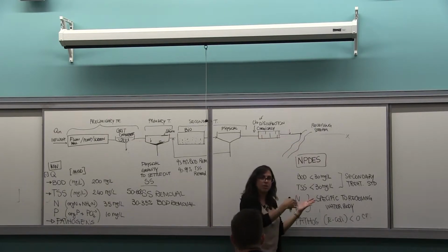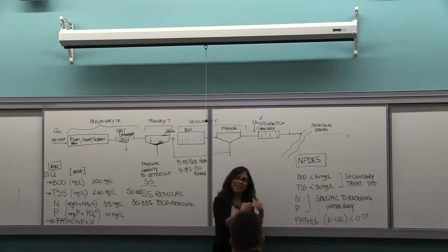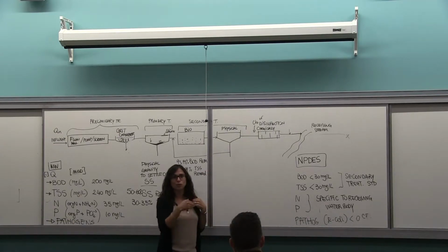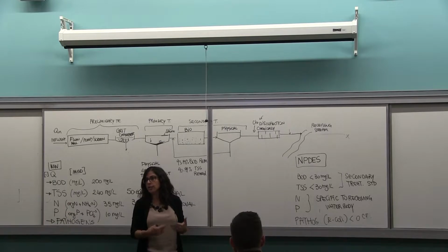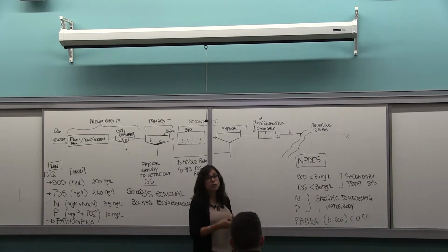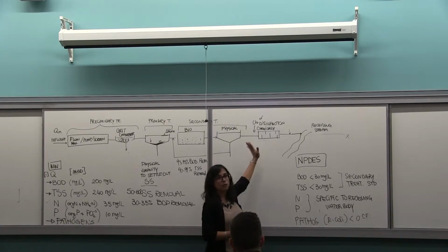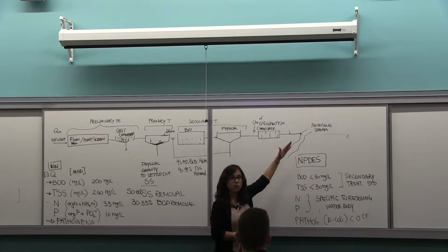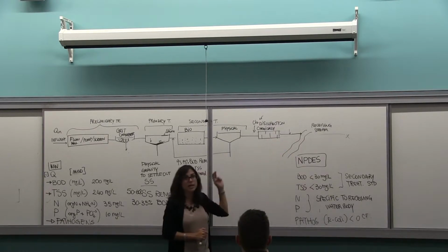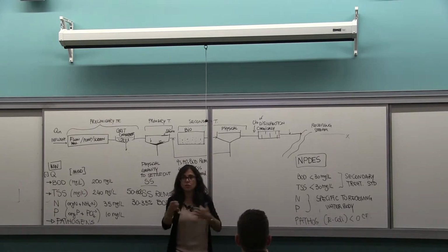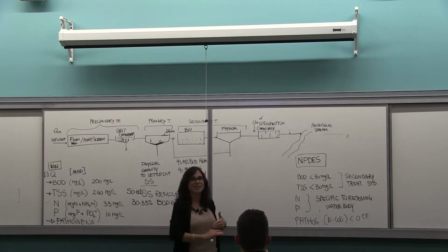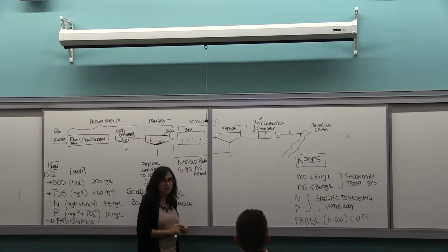So chemical addition and another chemical to eliminate the excess chlorine that is usually added to make sure that the pathogens are killed. If it's UV or ozone disinfection, then they don't have any residual, so you won't have to do any further treatment. But that's pretty much it. On the secondary standard, that's usually what the PE requires, just the secondary standard. All right? How about nitrogen?